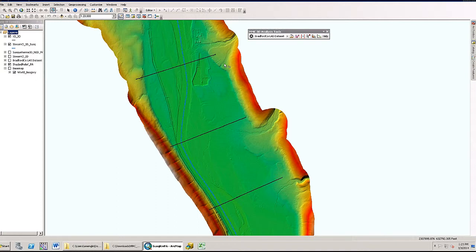The Digitize 3D Line tool will create a 3D line by interpolating elevations from the selected surface layer in the drop-down list. The Weed 3D Line tool will weed a single feature from a 3D line layer based on the tolerances set under the Configure Settings dialog. The Label 3D Line tool creates a temporary point layer labeled with elevations of vertices along a selected 3D line layer in the table of contents. The Identify Measure Elevation tool creates a temporary point layer with the measure and elevation labeled along a feature.